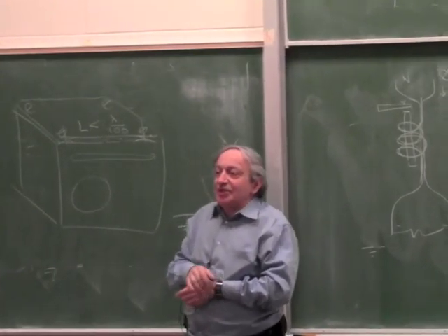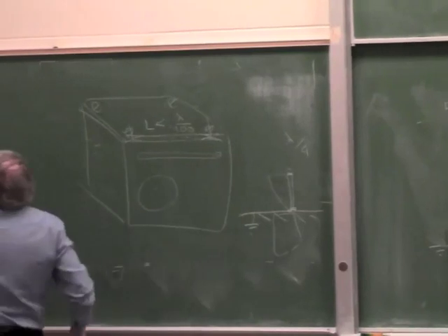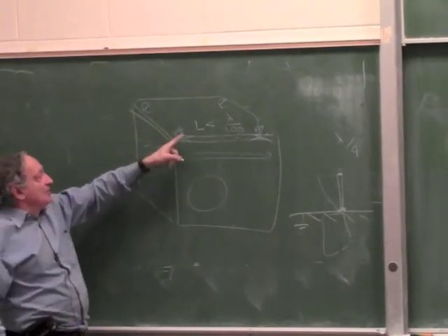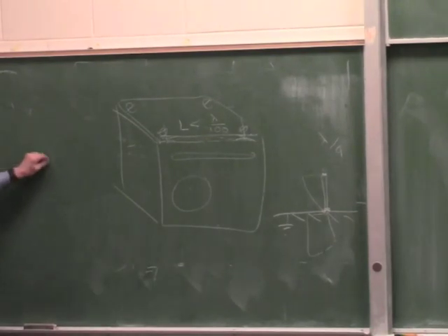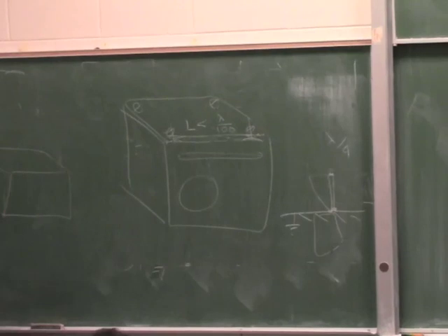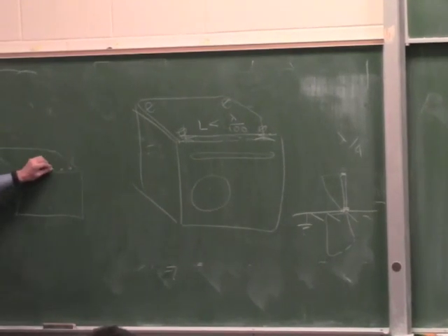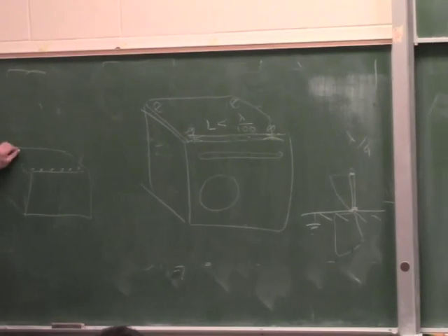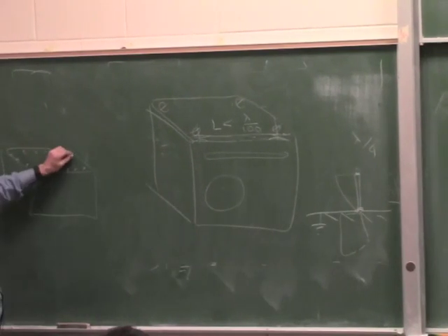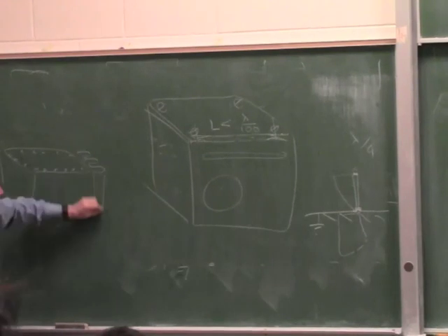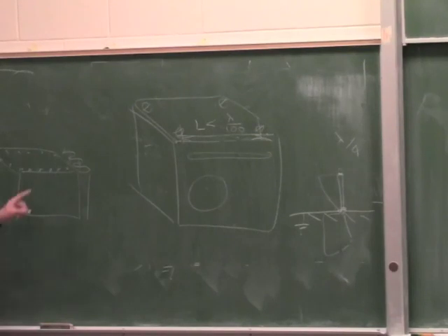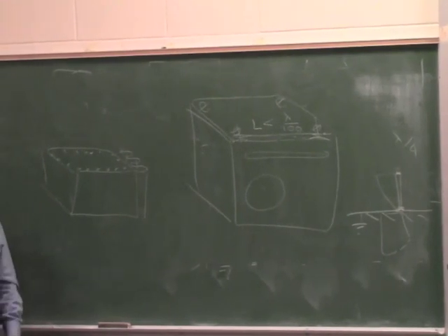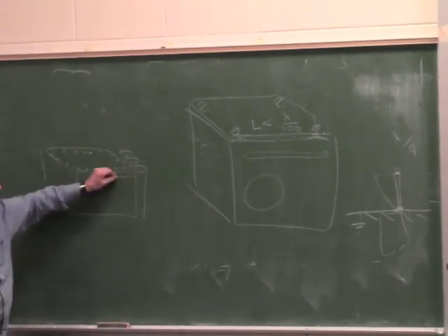And this is the reason when you look at an audio amplifier, it looks like this. It has maybe 4 screws on the cover, but if you ever look at an RF amplifier, because you can buy modular RF amplifiers, okay, they have maybe 50 screws. They have a whole bunch of screws all around the cover, and they have no ventilation slots. They may have fins, like a heat sink, but they have no slots for ventilation. Because everything has to be solid metal, and the cover has to be held down with many, many screws, so there are no gaps. And actually there's even a gasket underneath which conducts electricity.